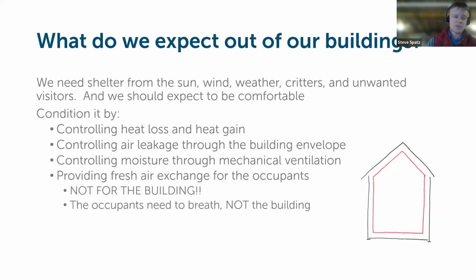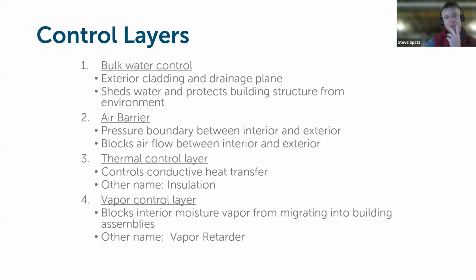And so there's no question anymore at this point about the need for having airtight building assemblies, because the more leakage you have through assemblies, the more moisture transport occurs and the more vectors for damage occur and the worse indoor air quality we get. So, that's a fundamental here of airtightness, which is a big key of what we'll talk about, but then managing the different aspects of the building assembly or the building indoor environment as a result of building airtight assemblies.